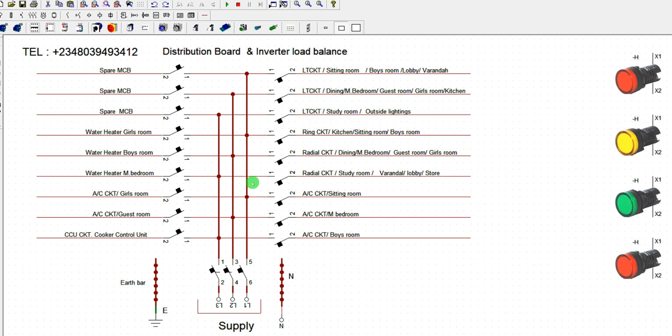If you do that, the load is no longer balanced, and some of our end users also need what we call backup power, a standby power source, the generator or any related source of supply. So if you do that, and the three phase is coming from the genset, you will no longer be balanced, and you are all aware that our three phase from the genset supply is expected to be balanced as evenly as possible across the distribution board.